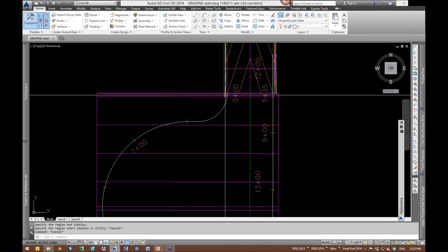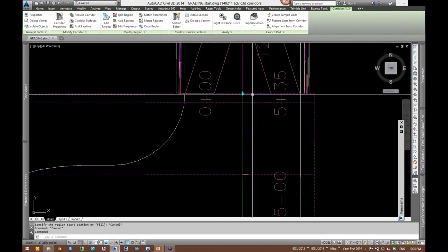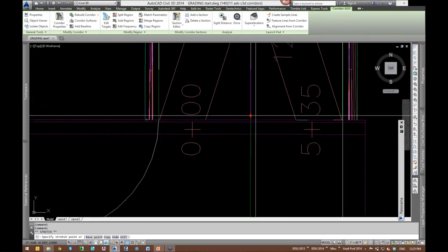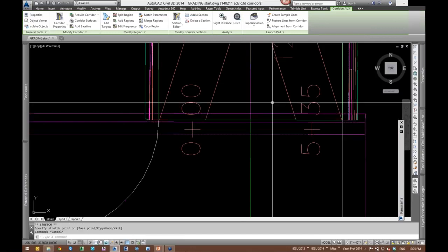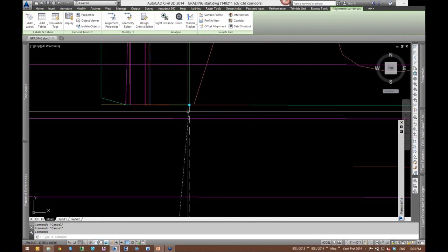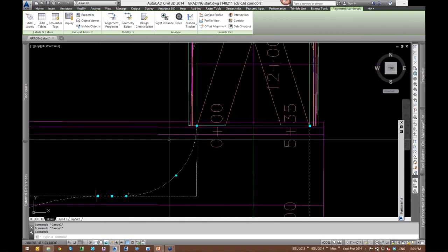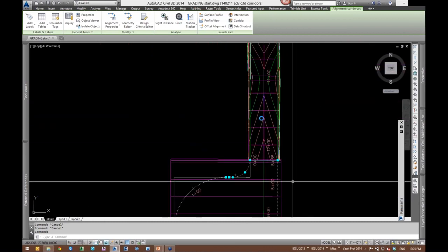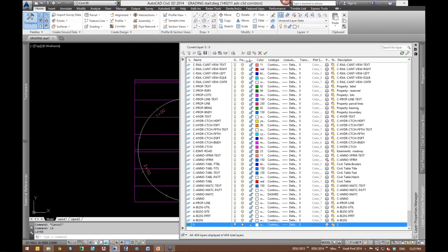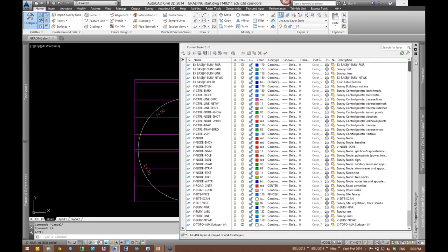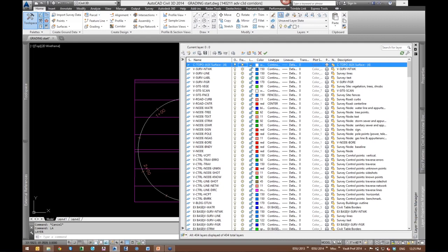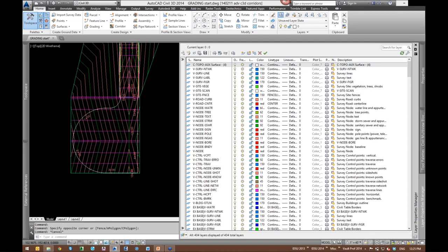I'm going to correct myself here. I said we're going to run this region a little bit past the actual cul-de-sac. So I'm just going to bring this up a little bit. And the reason is when we cut a surface profile, we'll be sure that it's within this auxiliary corridor region. So if I again go to my layers and I turn on that auxiliary surface, I should now see the general drainage of this cul-de-sac over here.